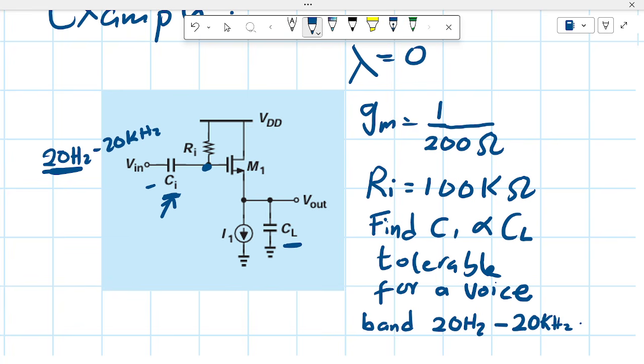So at this node, looking at the arrangement of the capacitor and the resistance from the node to ground, it looks like this node introduces a zero into the system rather than a pole, because with a zero, low frequencies would be rejected, just as we have in high pass filters as shown below.